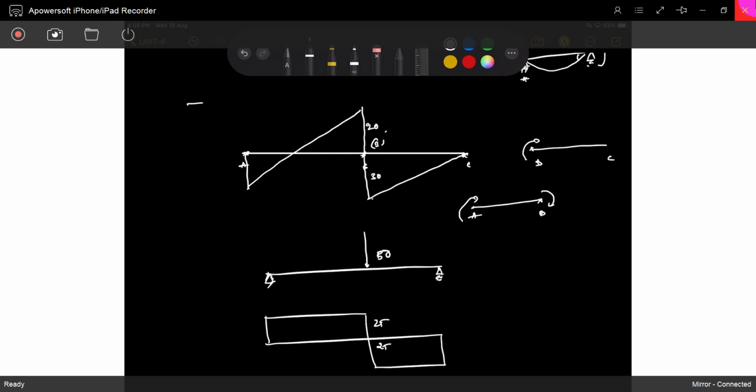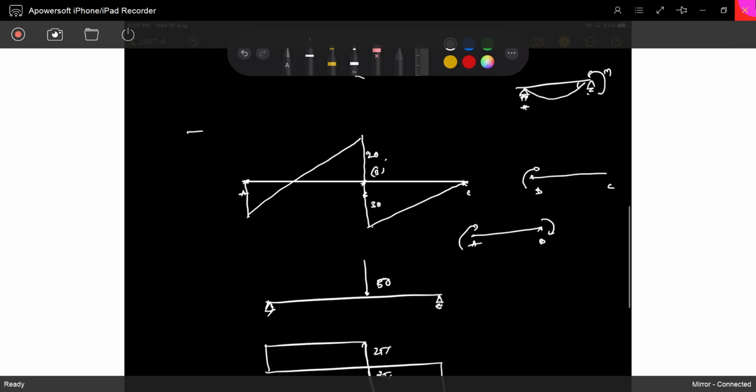If you observe it, exactly at that location a concentrated force is there. It is equal to 50. That's why we get 25 shear. But if we add just at that exact location, we get 50 of shear force. The same thing is here also. You can get the bending moment diagram like this. You can reverse it in the direction also. No need to write down bottom and below, below and top; that is your choice.